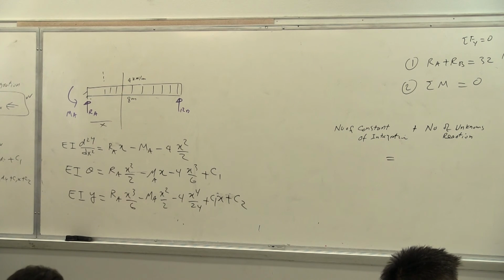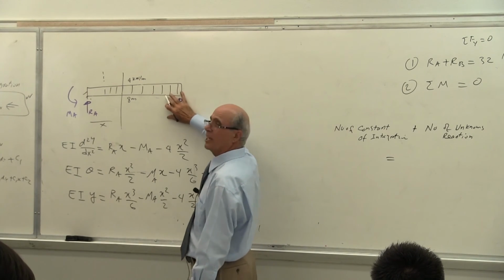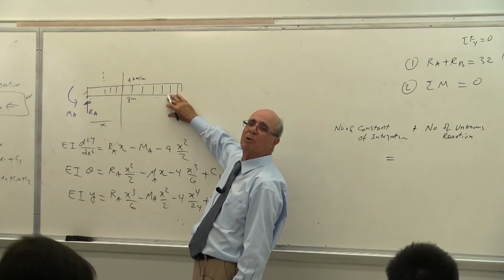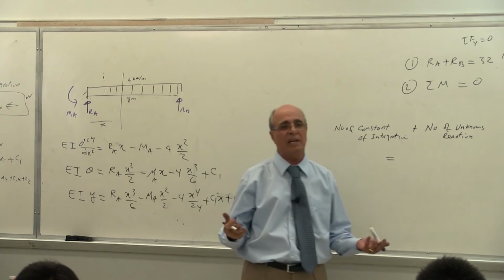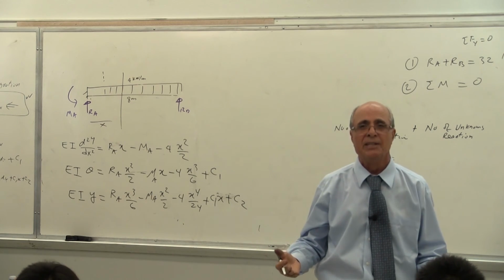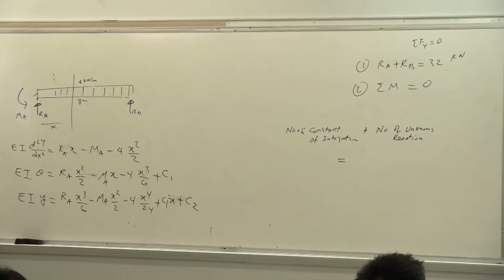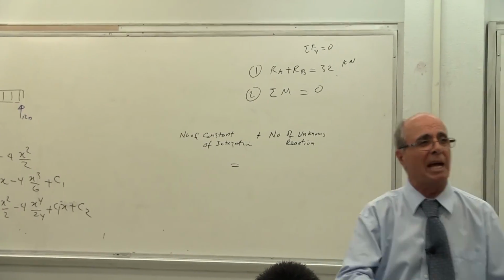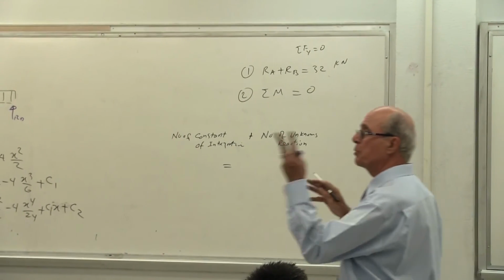It's very interesting. You have this RB there, put it there. Correct? If this RB was not there, this would be a determinate problem. It would have been no problem. Yes or no? You put an RB there, you made it an indeterminate problem. Then as a result, you have 1 more boundary condition, and that should be doing it for you. So it doesn't matter how many more unknowns you have, that many more boundary conditions you have. This time you have 3, not 2.